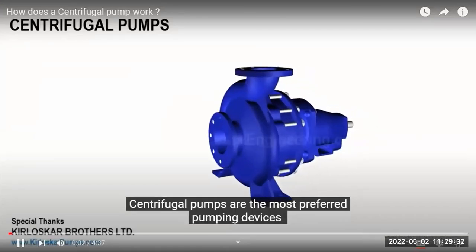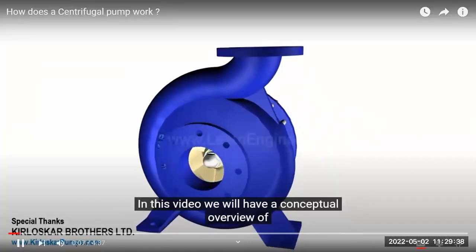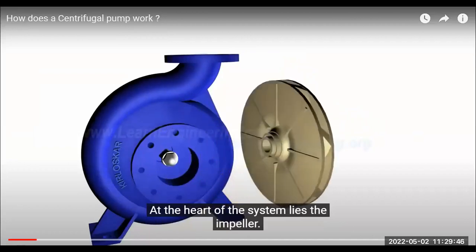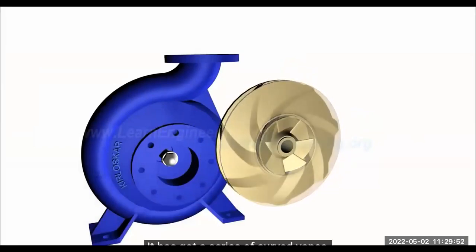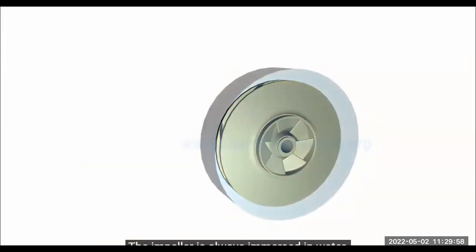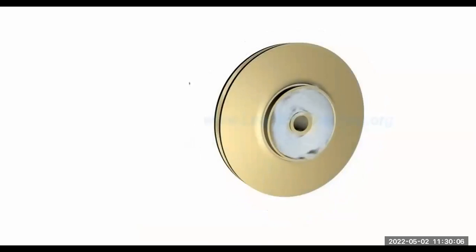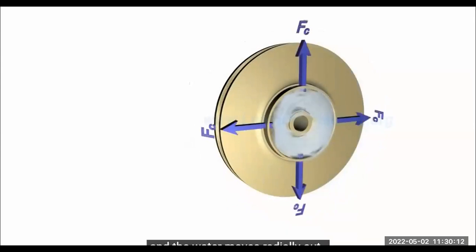Centrifugal pumps are the most preferred pumping devices in the hydraulic world. In this video, we will have a conceptual overview of working of centrifugal pumps. At the heart of the system lies the impeller. It has got a series of curved vanes fitted inside shroud plates. The impeller is always immersed in water. When the impeller is made to rotate, it makes the fluid surrounding it also rotate. This imparts centrifugal force to water particles, and the water moves radially out.